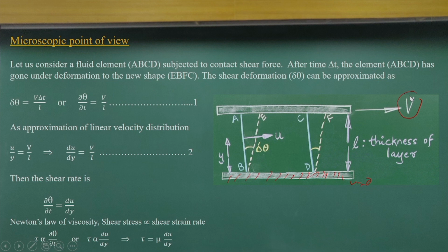As a microscopic point of view, I am not talking about the molecular motions or exchange of molecular motions, or the momentum flux that results in a shear stress. Here we consider a fluid element, that means I consider some space A, B, C, D. Whatever fluid is there in that region, I define as a fluid element.